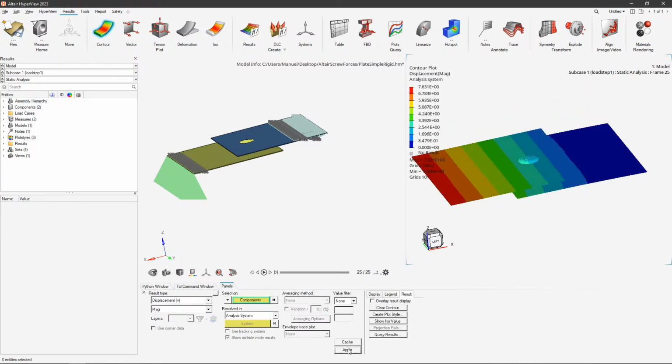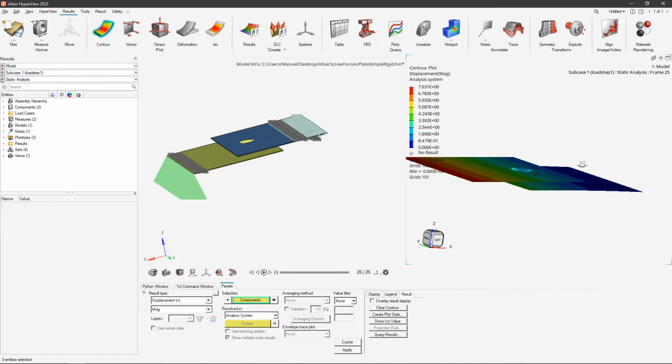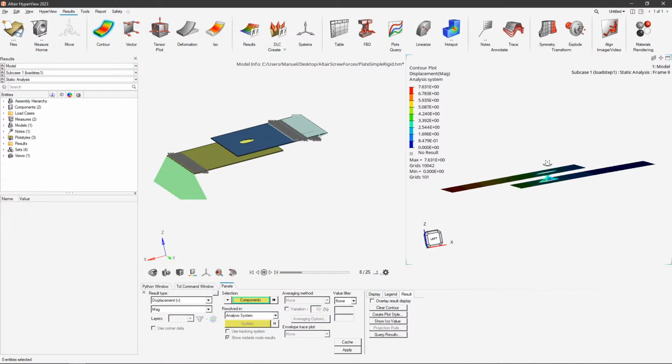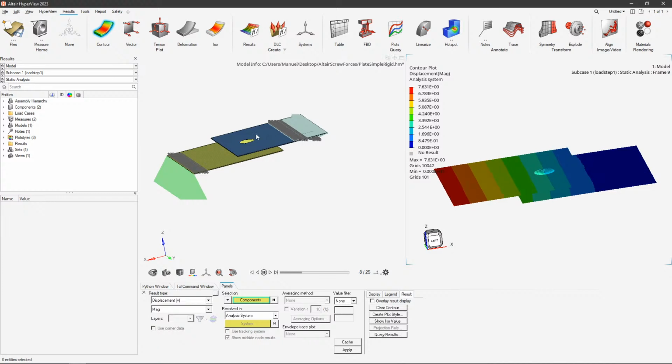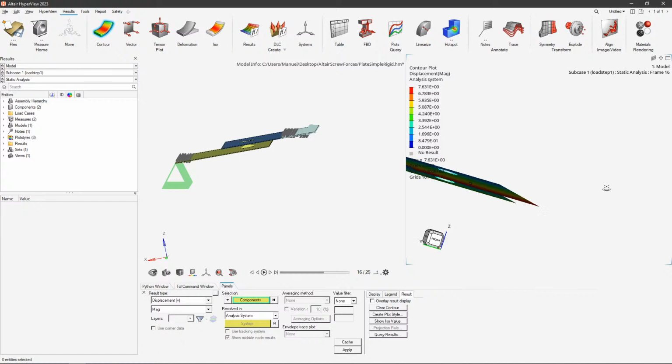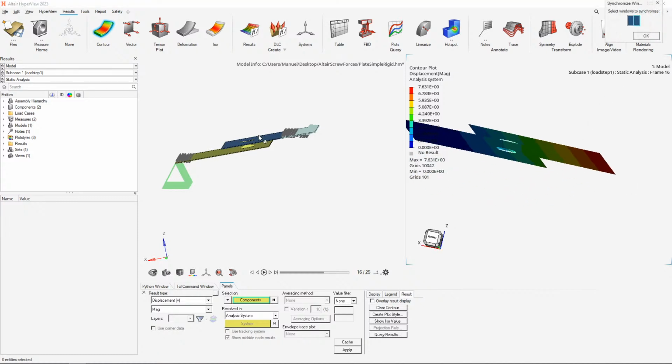Now, I would like to have the displacement, for example. I can see it's showing 7 millimeters. Okay, that's fine. Interestingly, it's moving down, because I have no support. Yeah, that makes sense. It's always good to check your intuition. It's not a tension case, because you have a tension, but then you have a lever, and that's bending it down. So this is exactly what's happening here. Let me synchronize this.